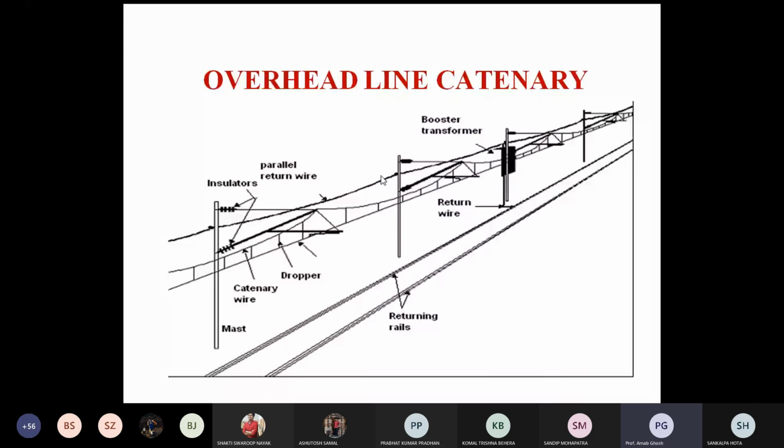Another thing is that battery pack or battery bank. That battery bank will be charged all the time from your overhead lines. Sometimes in that frequency mixing zone, when you switch off your main traction system from your pantograph, at that time who is responsible for emergency electricity and the emergency tractive effort or traction motion?